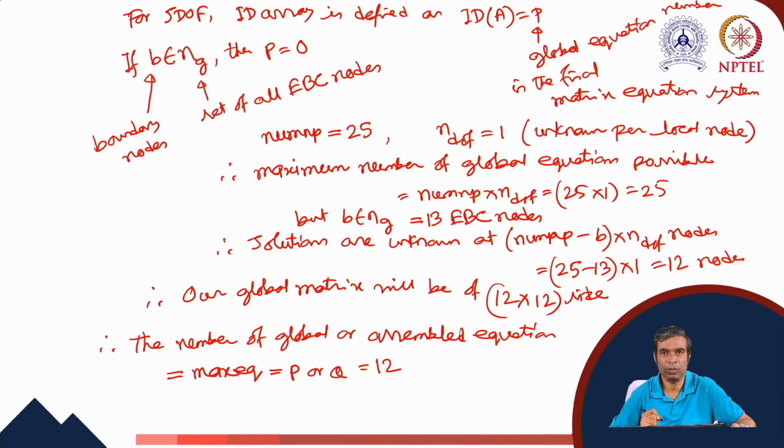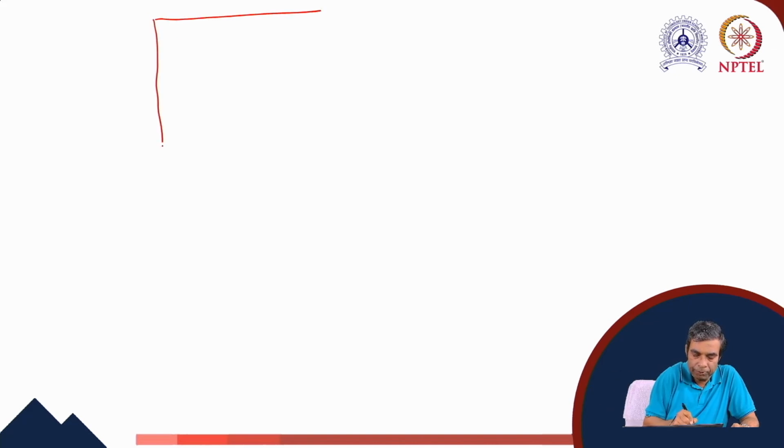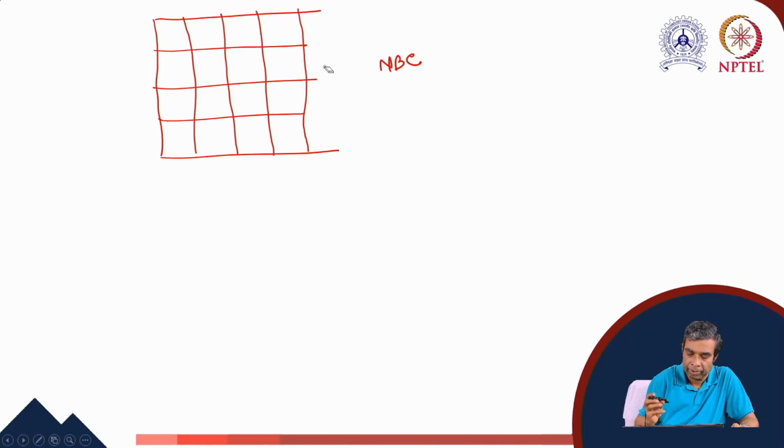Now let us construct the ID array. For the ID array, we again have to show the number of nodes and elements here, so we are again making the mesh. In this picture, the right boundary is NBC, the bottom boundary is EBC, the left boundary is EBC, and the top boundary is EBC.